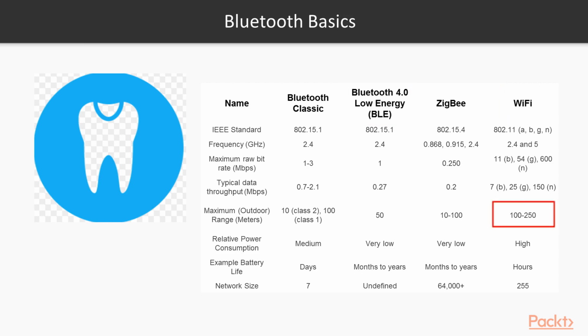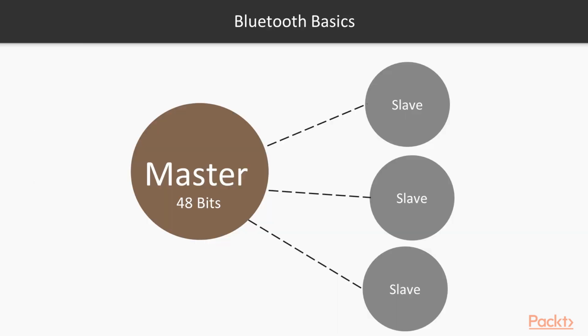The concept that works in Bluetooth: Bluetooth networks are also referred to as piconets, which have masters and slaves. Piconets use a master-slave model to control when and where devices can send data, and it always includes a Bluetooth address and a name. The Bluetooth address is normally a 48-bit unique address. The lower 24 bits are the more unique part of the address, and the other 24 bits are mostly the manufacturer or organization unique identifier.